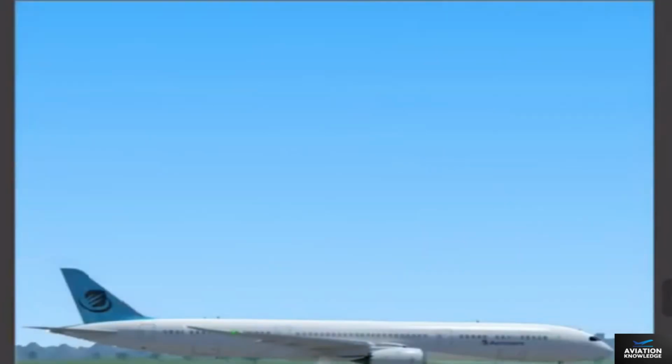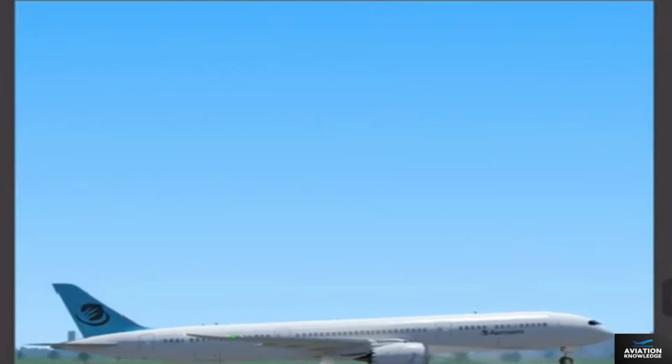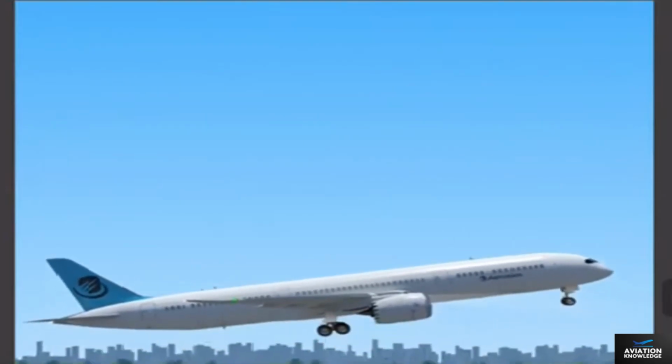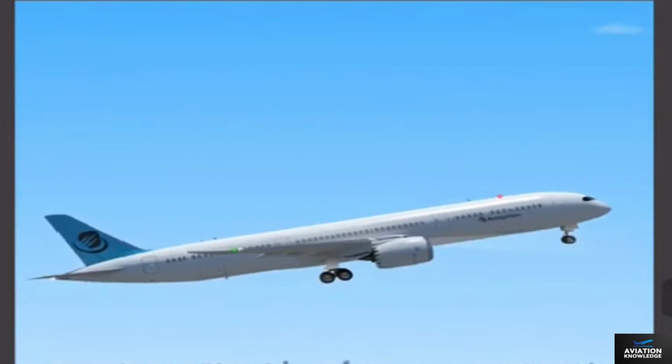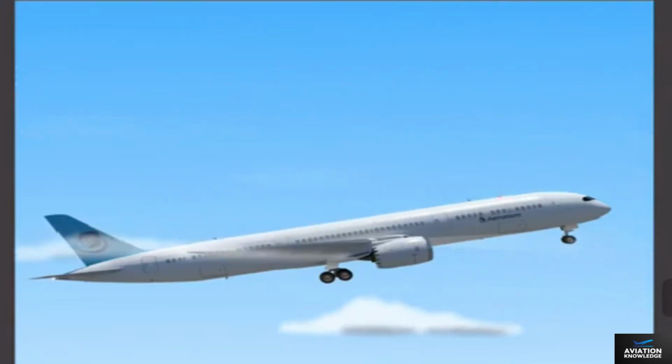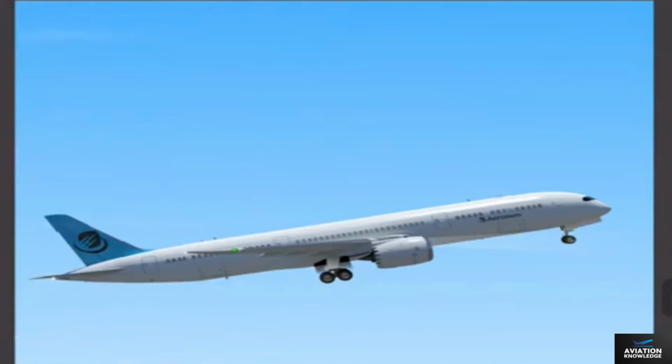During takeoff or landing, the PFCs calculate if a tail strike is imminent. If required, the PFCs decrease elevator deflection to reduce the potential for tail contact with the ground. Activation of tail strike protection does not provide feedback to the control column. If activated, takeoff performance will not be affected.